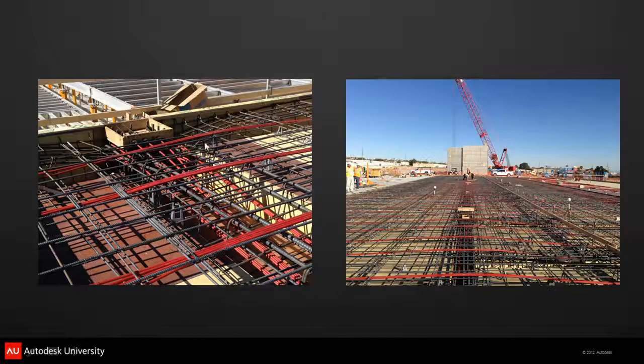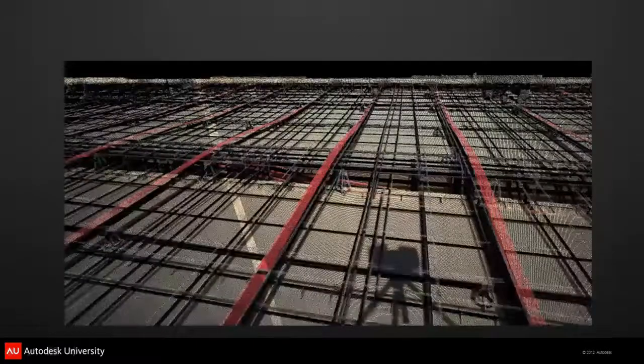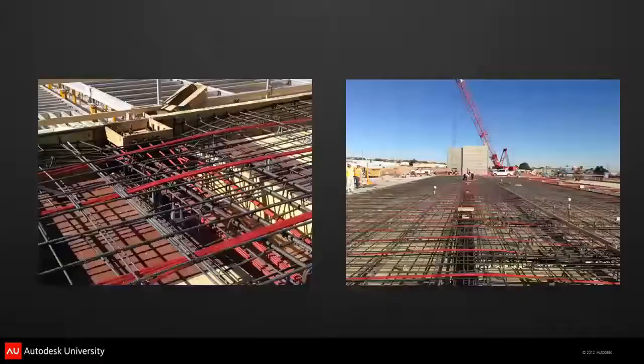And all of these PT cables are provided by the trade contractor. The structural engineer doesn't show those cables. They give a note and they say how much stressing needs to be applied. And so we were advocating to facilitate future use of plumbing and piping installation and electrical for other tenants that may happen down the road.